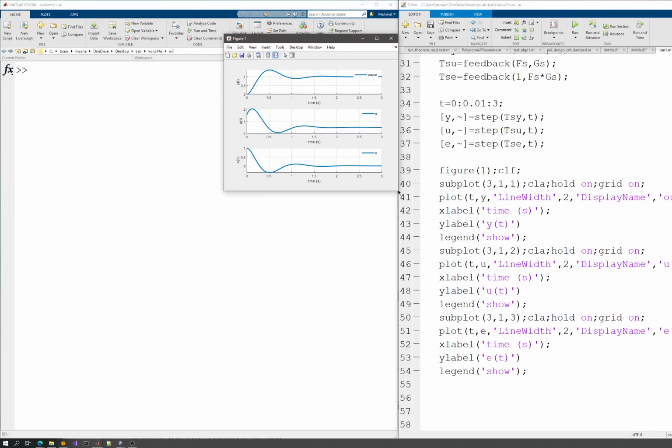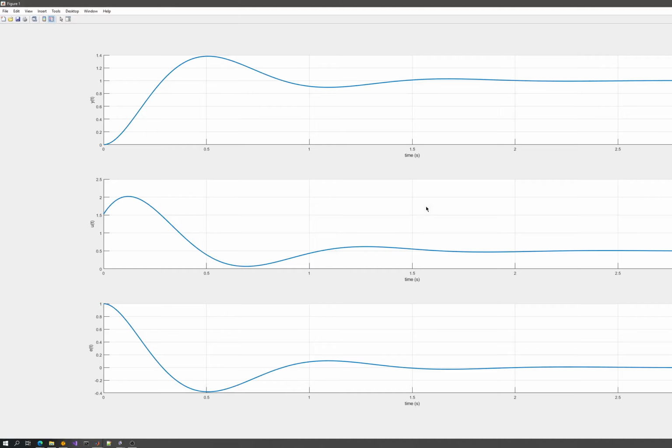Now, let's look a little bit closer at this. I see now that I have the following step response, and I can also see that my control signal starts with 1.5. It goes up, it goes down to 0. At this point, it crossed the reference, so it was almost there, but then it did go far away, further than the reference. So at this point, the system tries to compensate for that and applies a little bit more, and it repeats in a certain path, but there's a damping here and not a high damping.